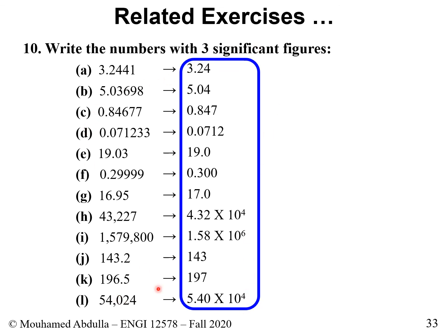So maybe I went quickly, but this is how we do it with 3 significant digits. For us, when we do labs and evaluations and so on, please always stick to engineering notation and also to 3 significant digits. Usually when we are in a lab environment and we're using different equipment, power supply, digital multimeter, oscilloscope, I always tell students any measurements that you get from equipment, use 4 significant digits, but if you use paper and a pencil or simulation, you could suffice with 3 significant digits. So please don't forget, when you do anything in this course, engineering notation, and stick to 3 significant digits.